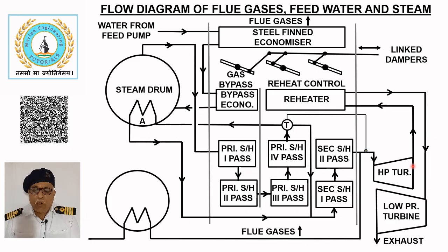The exhaust steam from the high pressure turbine, having a reduced degree of superheat, is returned to the reheater to raise its temperature before entering the low pressure turbine, which exhausts into the vacuum condenser. Reheating prevents turbine damage caused by erosion and corrosion due to moisture formation.